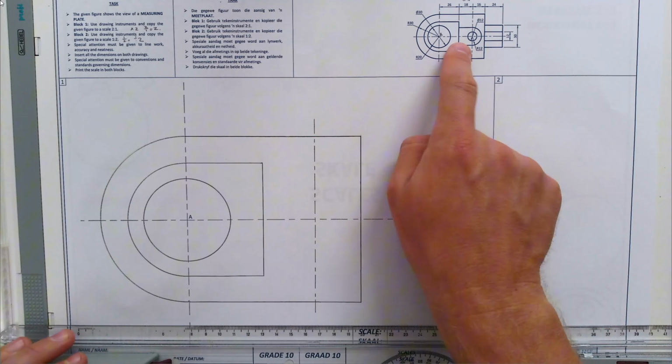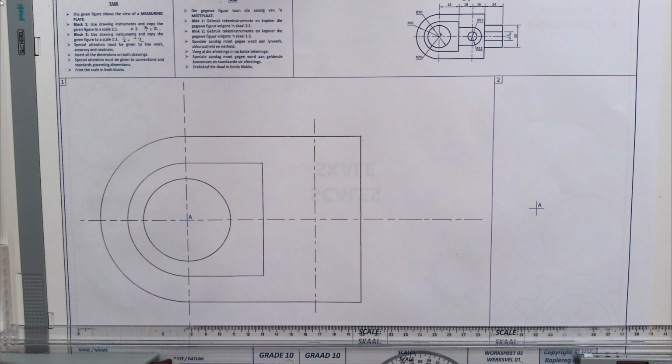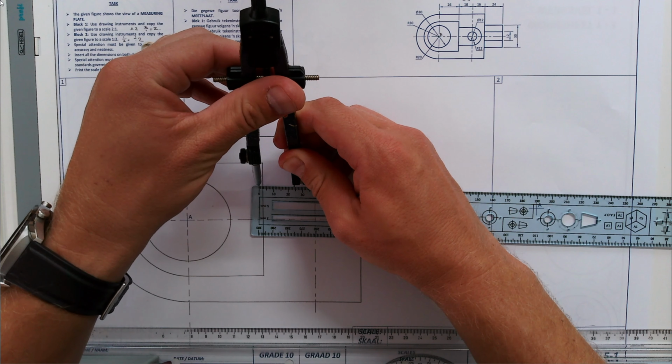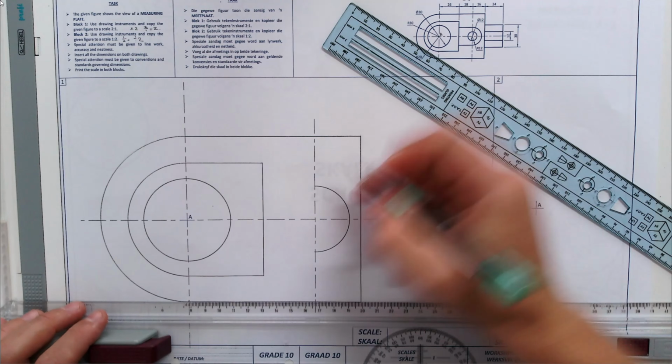Then this has a radius of 12. 12 times 2 is 24. Take your compass. Set this to 24. Sharp point in that middle point. And then go put in that half circle from there to there, as seen on the given information. Nice and solid. That point and that point we can take back all the way against that line.